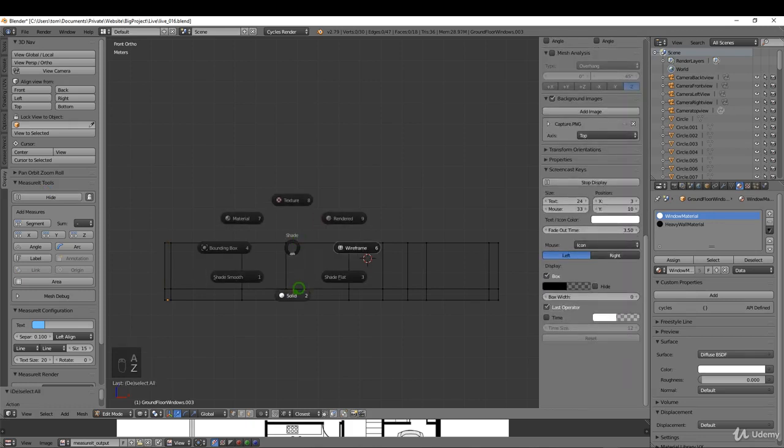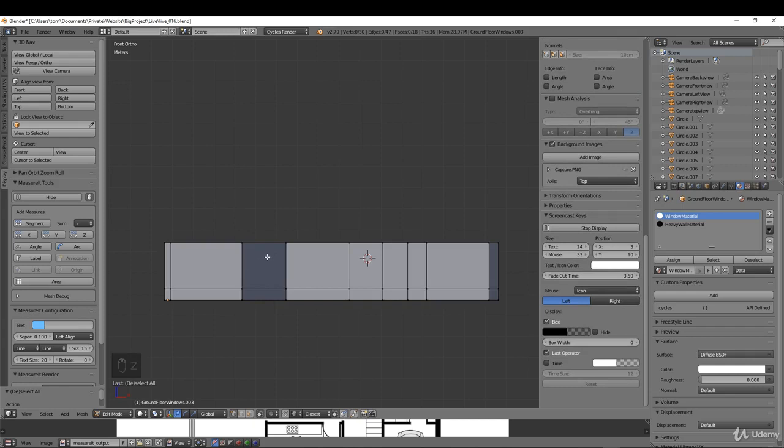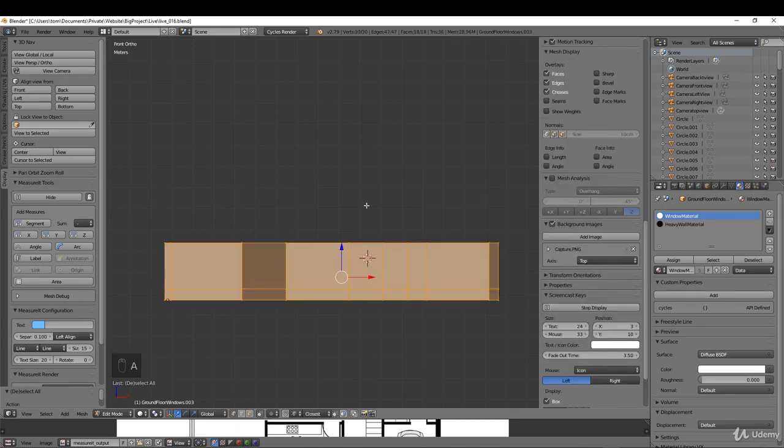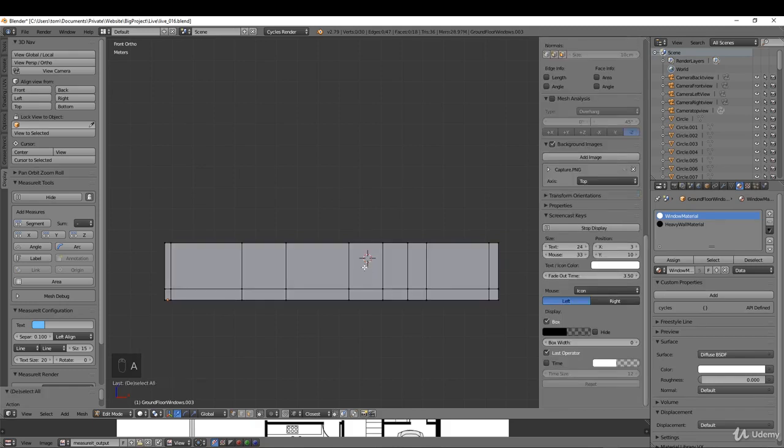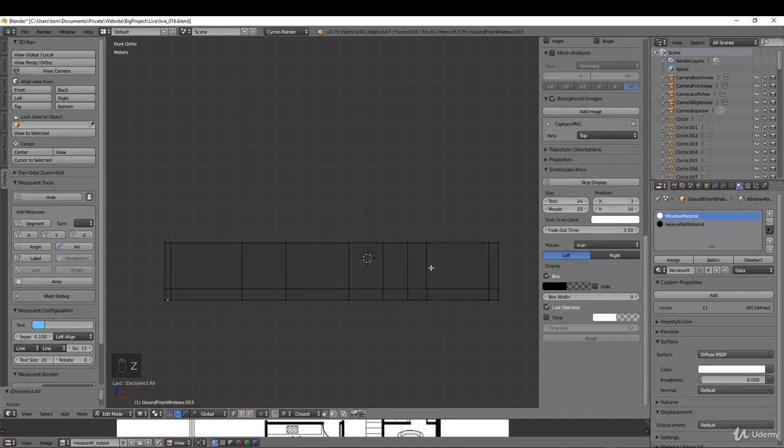I'm going to press Z now for solid shading, and you can see we have a couple of faces pointing in the wrong direction. You notice that by the shading. So I'm going to press A once or twice, select all the faces and press Ctrl N to recalculate the normals. Okay, and they're now fine. So if I just deselect them, I'm going to press Z and come back to wireframe.